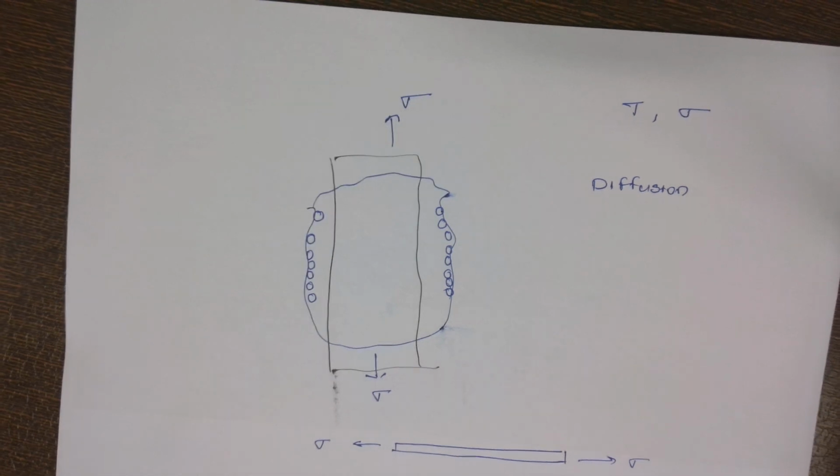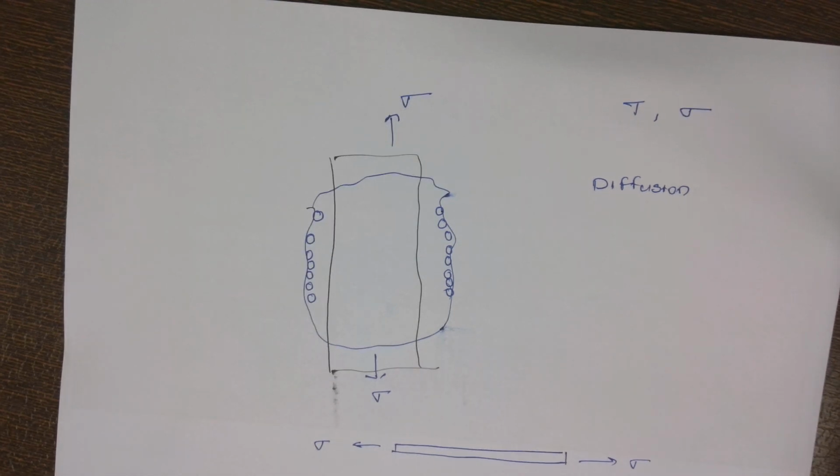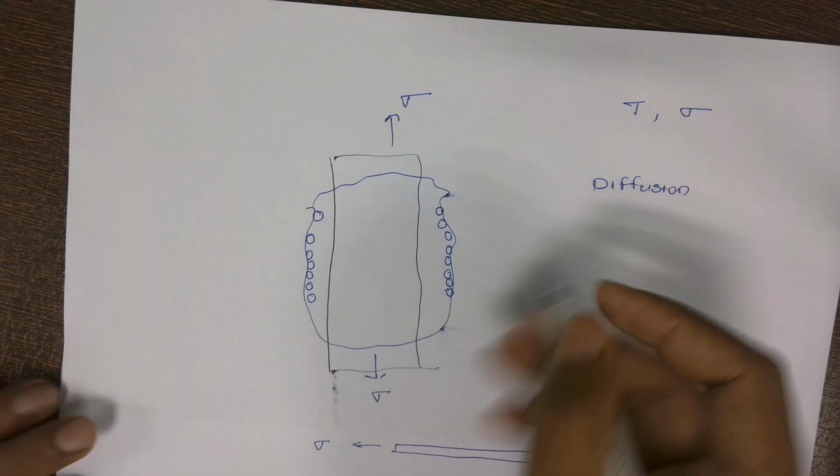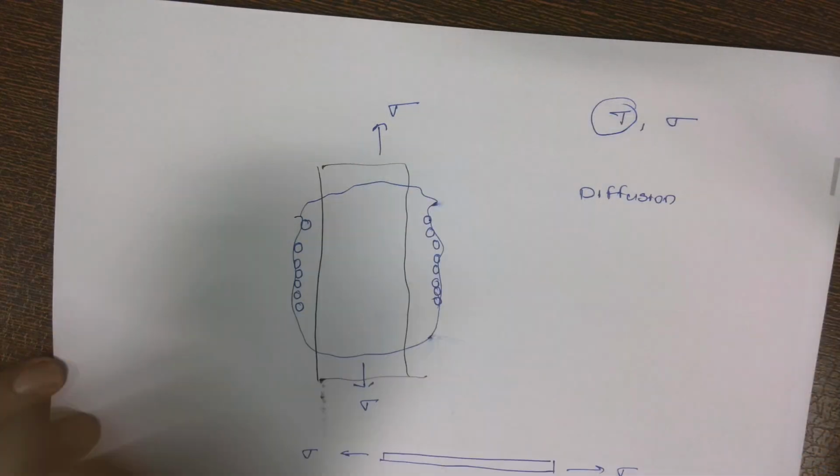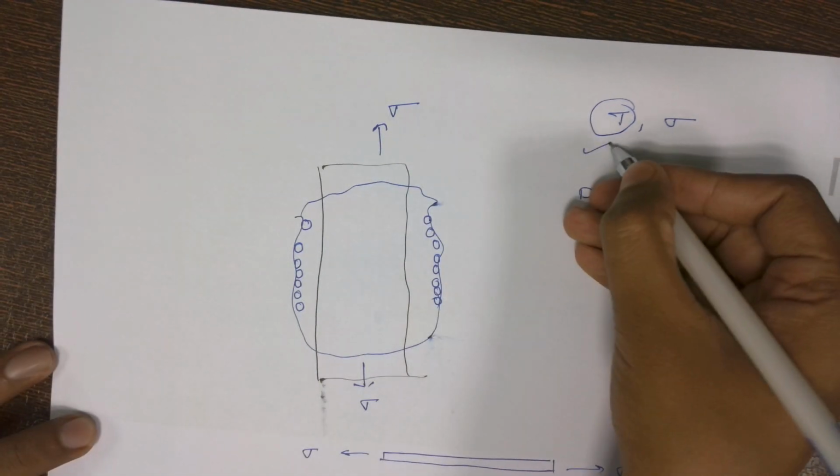We saw in class, I think in week 6 or week 7, that if you go to high temperature, the vacancies will be more and more, and that's the reason our vacancy migration can happen. An atom can migrate. So when we went to high temperature, the diffusivity increased.